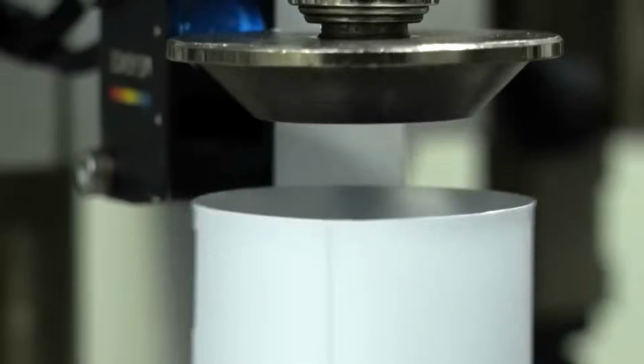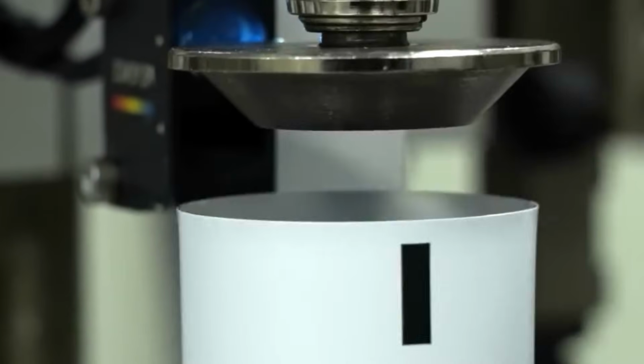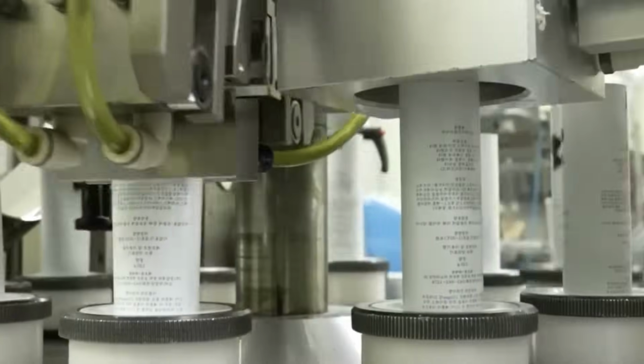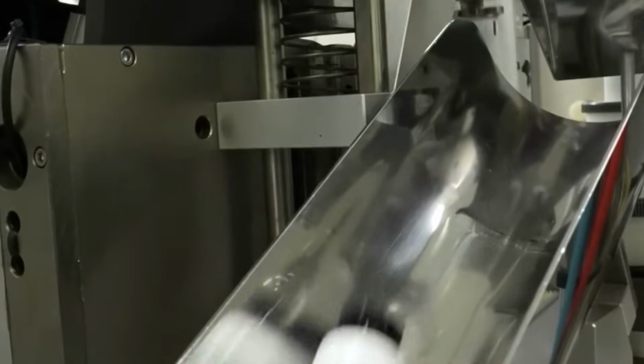The entire vessel is held under partial vacuum to remove entrained air. A vacuum pump system pulls air through condensers and liquid traps. Vacuum mixing prevents bubble formation, ensures uniform density, and improves the shelf stability of the final product.